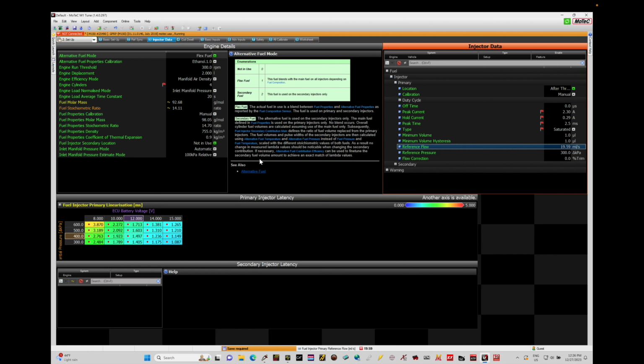Okay, so the very first thing we need to understand is that we have this fuel and airflow model that we've talked about pretty extensively up to this point. We have fuel mass is equal to air mass divided by our target air fuel. Now we know our air mass is going to be an estimation of air mass. It's going to be derived knowing number of cylinders, engine displacement, the charge temperature, which is our density. It's going to also take a look at our MAP pressure and our volumetric efficiency percentage coming from our volumetric efficiency table. So all of that establishes our air mass, or the amount of air mass coming into our engine at any given time.